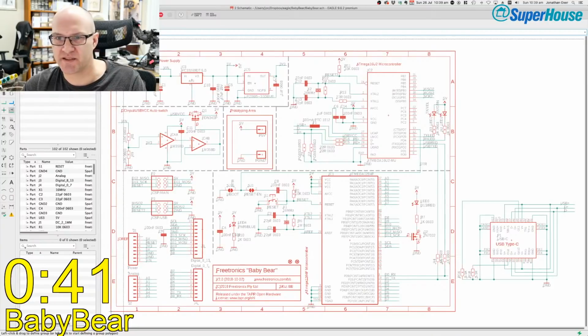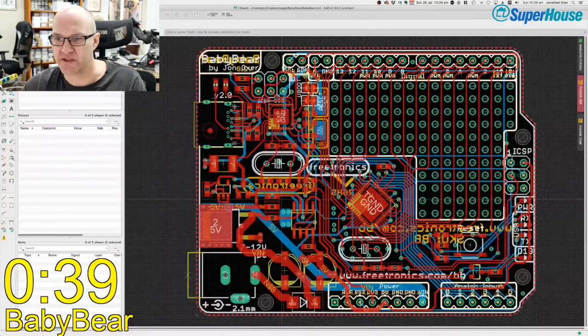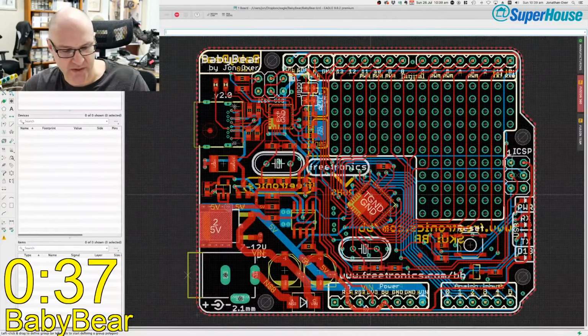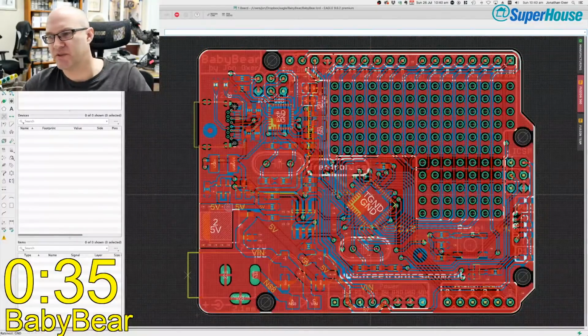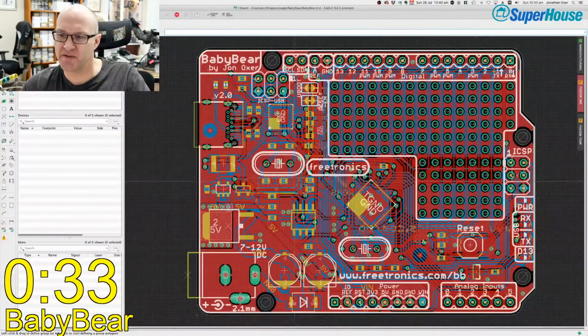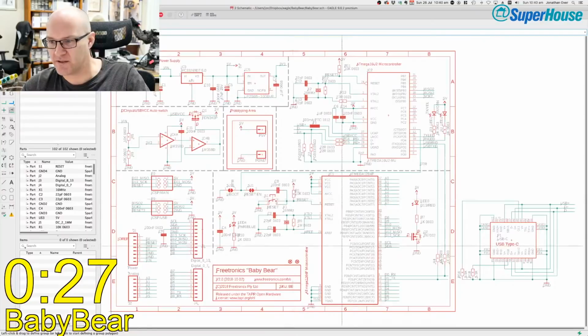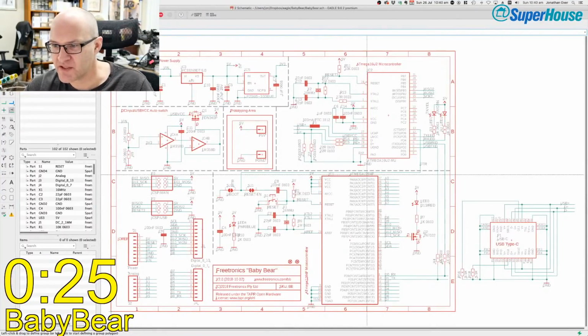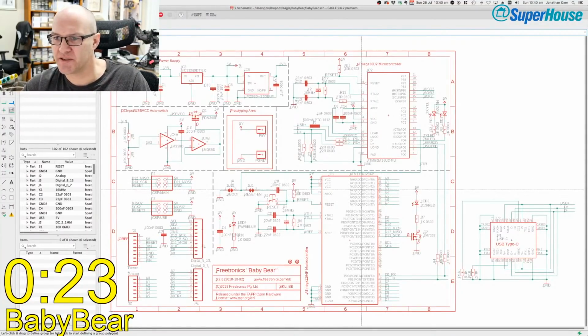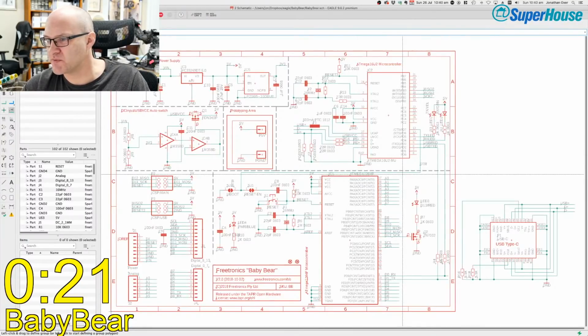This is the project that I talked about a couple of live streams ago. It is an Arduino compatible board. It's actually almost the same as an Arduino Uno. The only difference is that it has a different CPU on it, so that it has lots more memory. It's got an ATmega1284P on it, but apart from that, it is a direct replacement for an Uno.